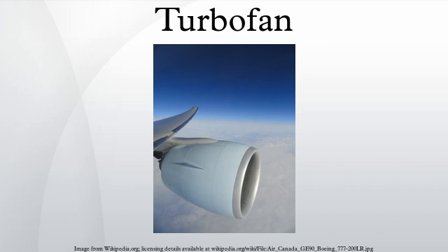Aft fan turbofan. One of the earliest turbofans was a derivative of the General Electric J79 turbojet, known as the CJ805-23, which featured an integrated aft fan low-pressure turbine unit located in the turbojet exhaust jet pipe. Hot gas from the turbojet turbine exhaust expanded through the LP turbine, the fan blades being a radial extension of the turbine blades. This aft fan configuration was later exploited in the General Electric GE36 UDF demonstrator of the early 80s. One of the problems with the aft fan configuration is hot gas leakage from the LP turbine to the fan.